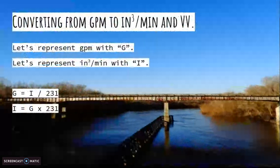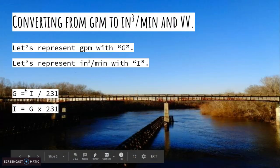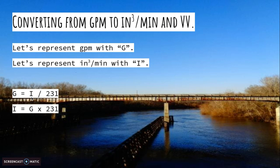In certain cases, we'll talk more about this in the next lesson as well, you'll have to convert from gallons per minute to inches cubed per minute, and vice versa. So let's pretend that gallons per minute we'll represent with G, and inches cubed per minute is I. So these are the two equations. To convert to gallons per minute, divide the inches cubed per minute by 231. To convert to inches cubed per minute, multiply the gallons per minute by 231. So that's what you can do.